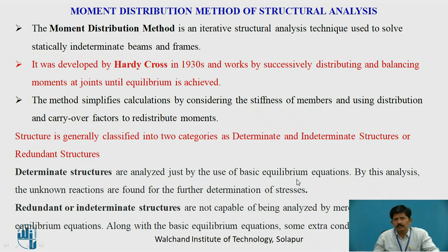The basic equilibrium equations are summation of Fx equals 0, summation of Fy equals 0 and summation of M equals 0. Whereas the redundant or indeterminate structures are not capable of being analyzed by merely using equilibrium equations. Along with the basic equilibrium equations, we require some extra conditions. These are called indeterminate structures.